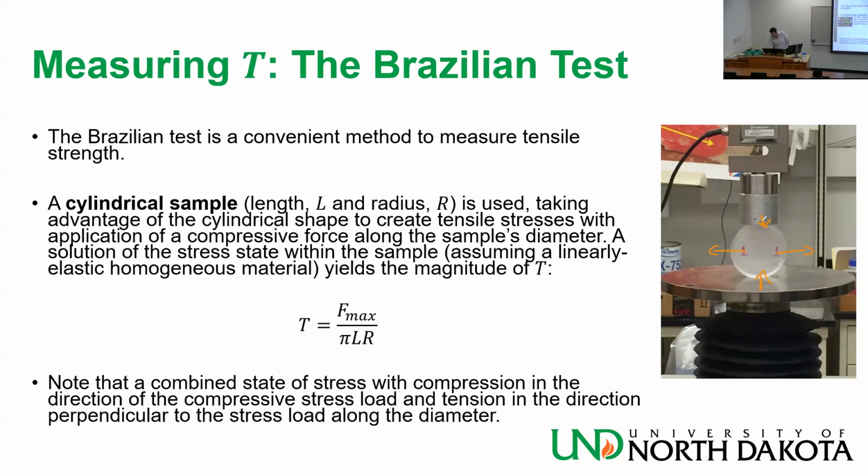Yeah, so it's gonna fail like this, 90 degrees in tension. So you apply compression because this machine is good for compression, and the rock samples are easier to apply compression on. But it's gonna fail in tension because of the indirect nature: you apply compression, but you get tension this way. That's why this Brazilian guy was very smart. He thought about it in a different way.